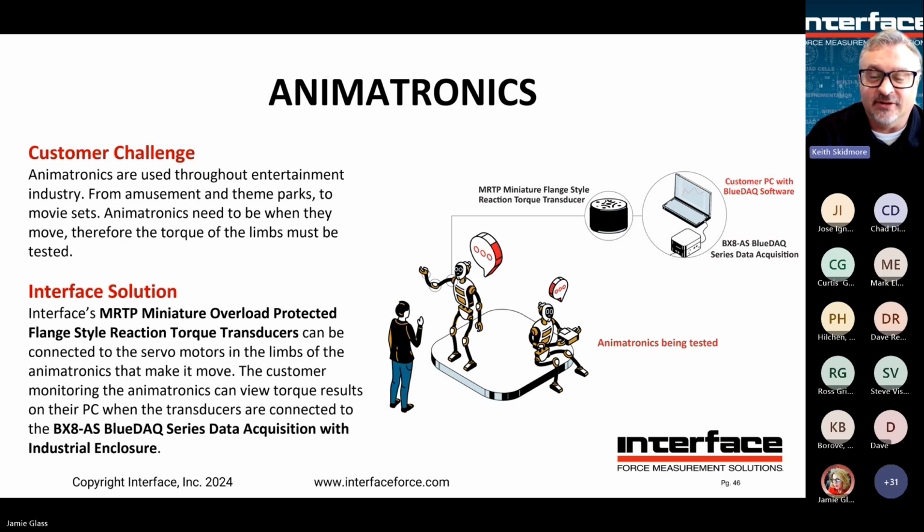Initially, what they'll be doing is taking data, so you have the item go through a motion and then take force or torque feedback and log that and analyze it and see what's happening. It might be that the joint creates torque spikes, which show up as torque spikes, but also show up as jerky movement or not as realistic as possible. So analyzing the data allows for better control algorithms to be created.